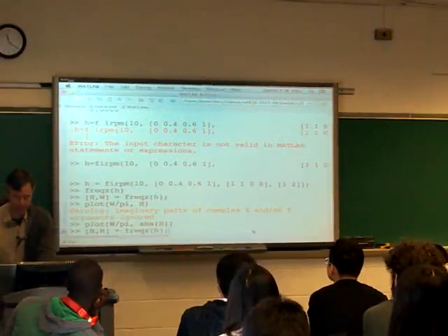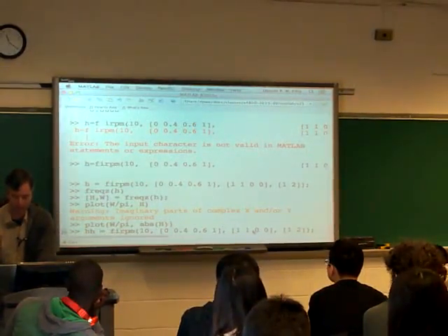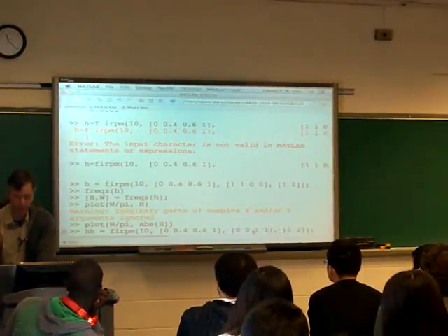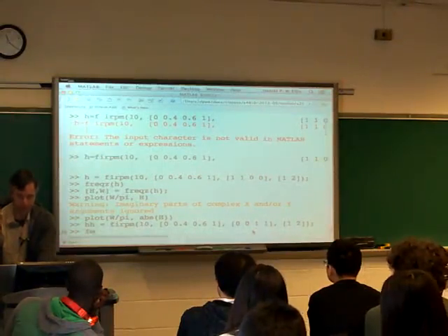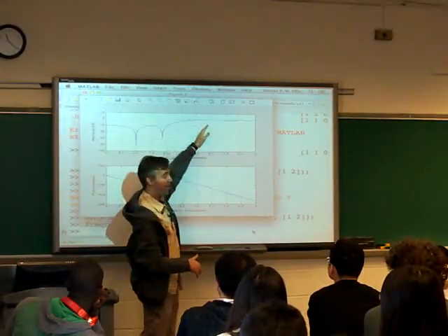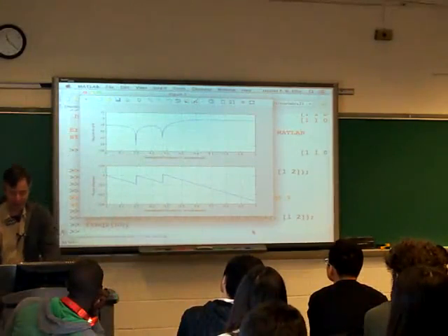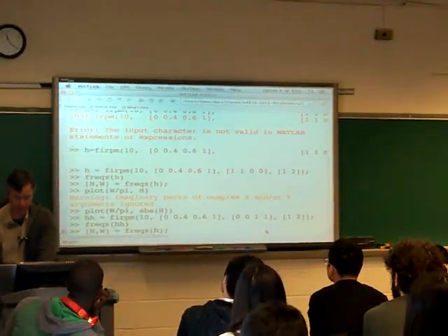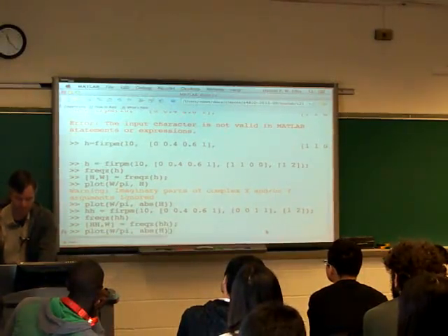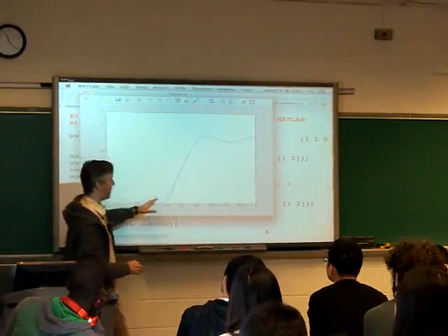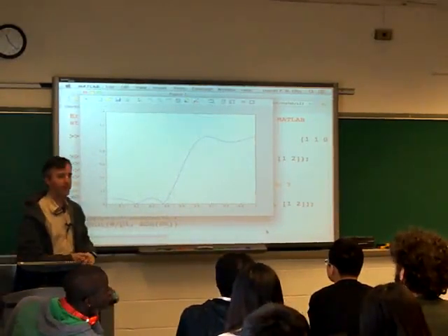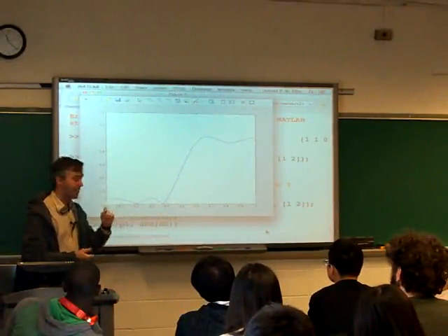Now if I did a high-pass filter like this, where I did zeros here and ones here, it's the same kind of thing, but now I have the high-pass response up here. And if I look again on a non-log scale, you can see that it is the complement of that response. Yeah, so you can specify the dB of the... Right, exactly. Good, thank you.